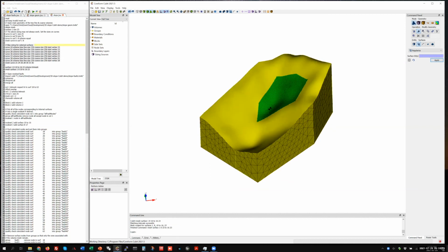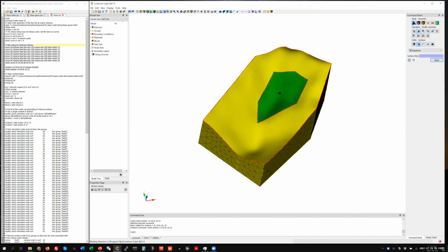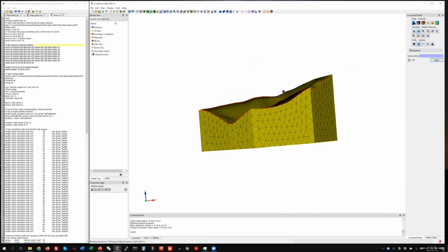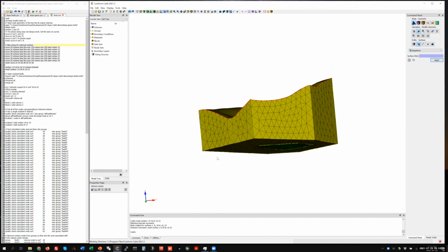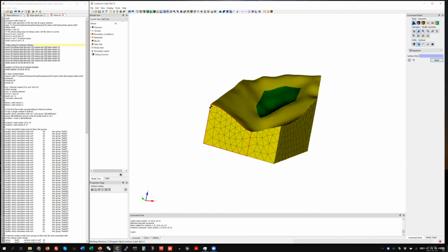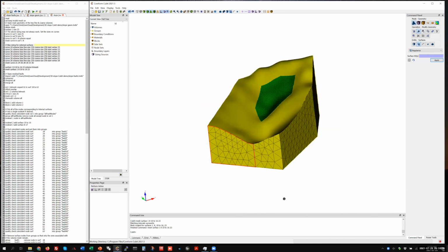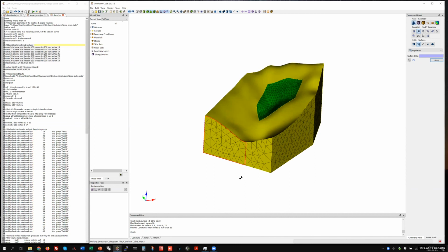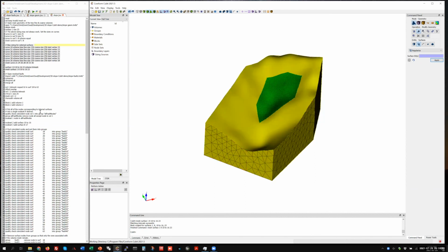And then I just mesh some of these surfaces. I don't mesh all of them. I just meshed the slope surface in the fine volume and all the external surfaces here. Okay. And I'm also using a bias, so I'm increasing mesh size from top to bottom on the external boundaries. Okay, I'm usually pretty aggressive in this because, as I said, you could really save on the number of elements this way. Okay, the next stage is to bring in the faults, and in this case, let's just do that. Please select it.